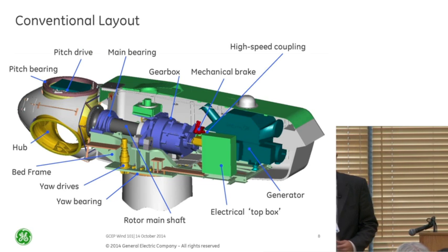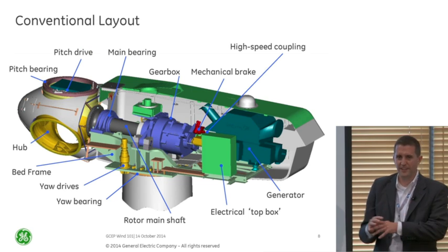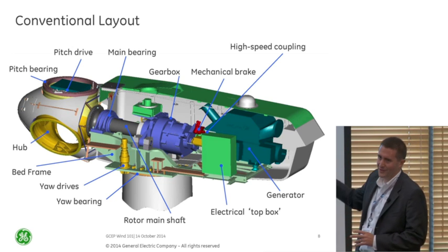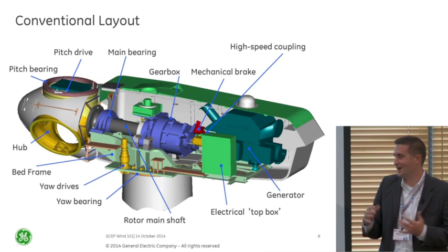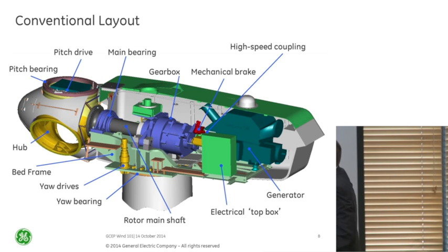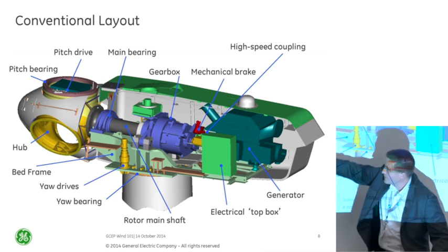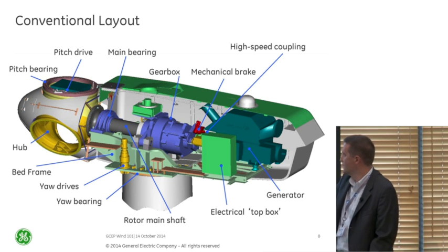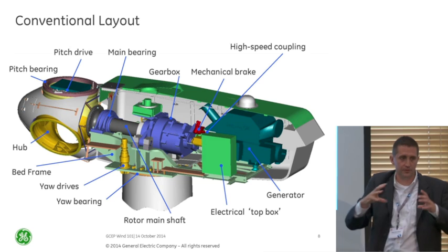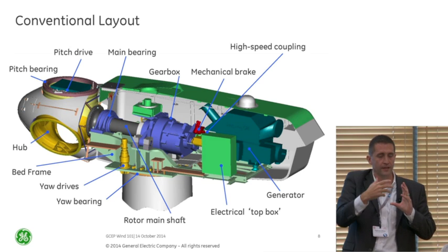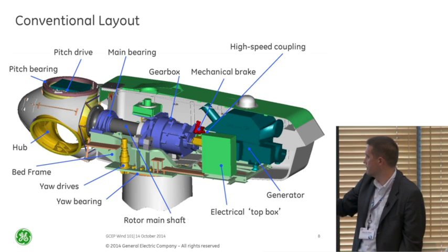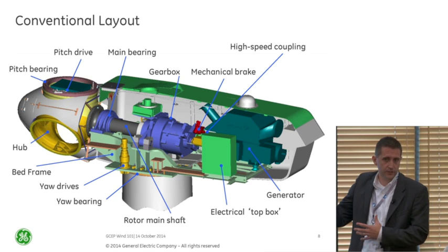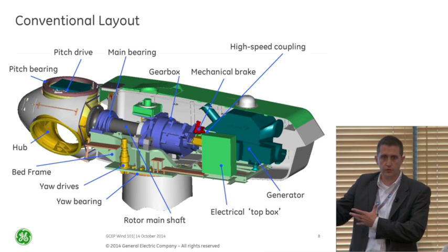All right, so I wanted to show you a cutout of, really, I did say it's really simple things, but I'm going to cut this out to show you that there are quite a bit of moving parts. I talked a little bit before about the pitch blades, so you can think of the blades coming out of here, that's the mechanism that's going to be able to turn the blades. It's connected to the hub, so the hub is the middle thing that's going to rotate around with the blades, but it's going to be the structural piece that holds it all together. It's going to run through a shaft into a gearbox. So this is a case of a geared one. If you didn't have a geared one, a direct drive one would go straight into a generator.